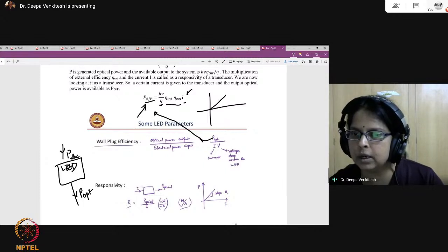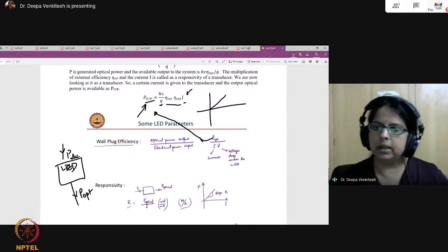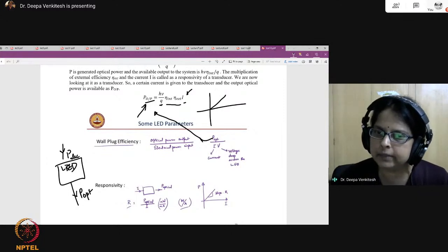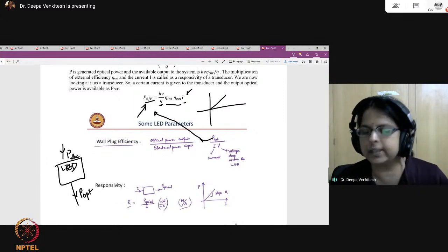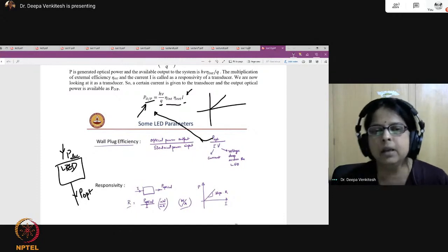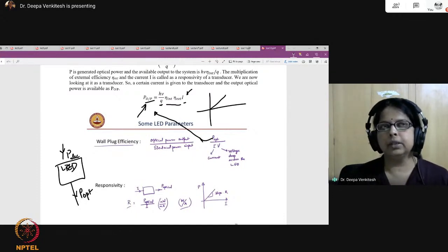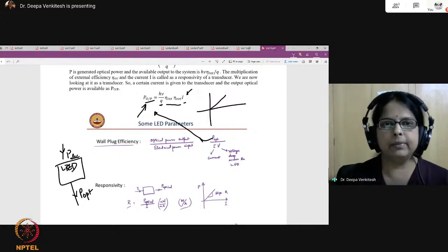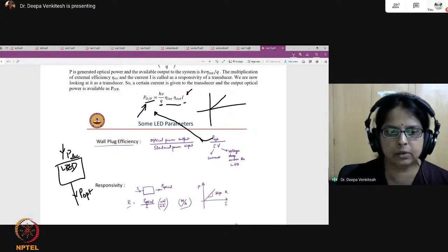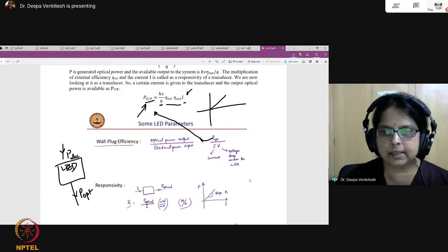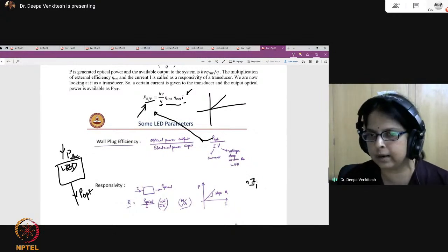Arjun, so yes, the dome does not improve the external quantum efficiency. It effectively redirects whatever fraction of light is transmitted. That is absolutely right. So the dome is not really to improve the quantum efficiency in that sense. Well, in one sense, you can improve quantum efficiency if you smartly place the dome in such a way that, for instance, if this is the material, it comes out, but then you don't allow this. So if this is plastic, this is refractive index n, and this is refractive index 1, and so you had calculated the Fresnel coefficients that way.